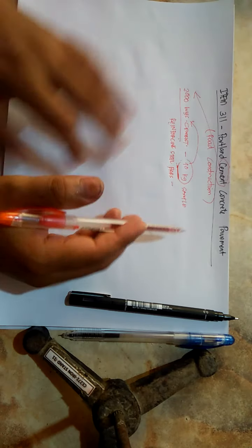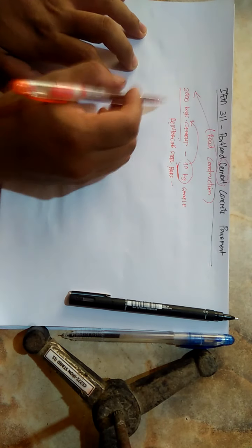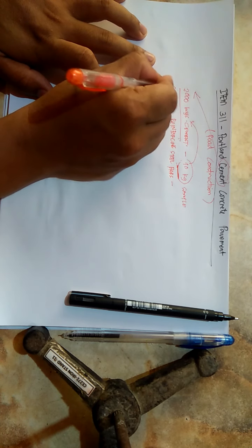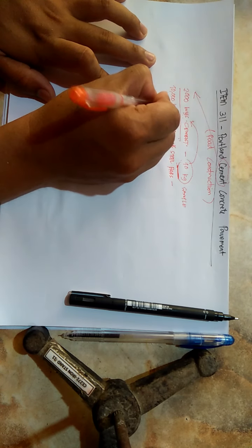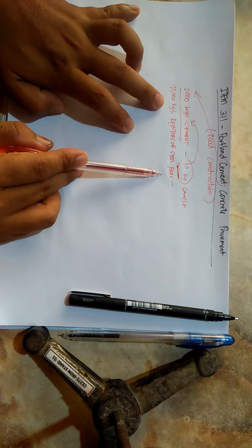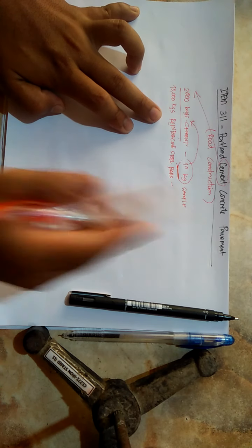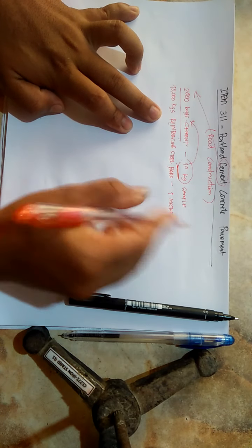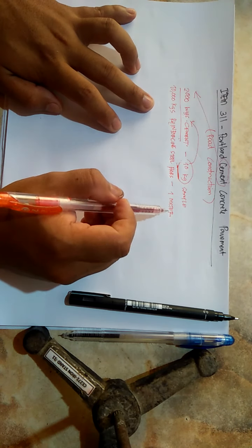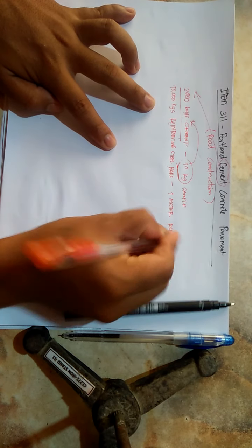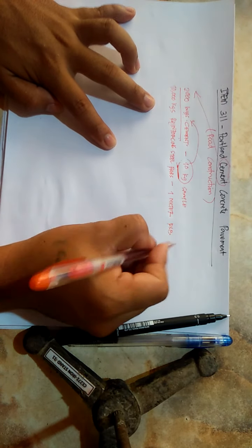Okay? Like for example, sa construction site, nag-deliver sila ng almost 10,000 kilograms. 10,000 kilograms na reinforcing steel bars. Ang minimum requirement na kailangan mong patest dyan is almost 1 meter. 1 meter ang ipapatest mo for your reinforcing steel bar, 1 meter RSB.